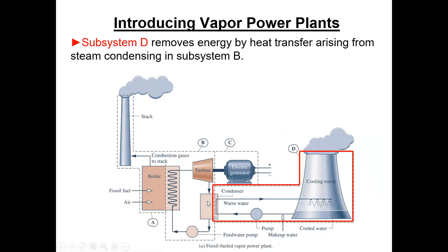That becomes a compressor, and the amount of energy required to return a vapor through this thing is just way, way too much. The pump energy in this Rankine cycle would be probably 1.5%, at most 3%, of the turbine output. If that was a compressor, that could be 30, 40, 50, 60%. So it's just way too much. So in order to use the same working fluid around, for purification, and there are lots of reasons, we have to condense. That's where the major energy loss is from this Rankine cycle.